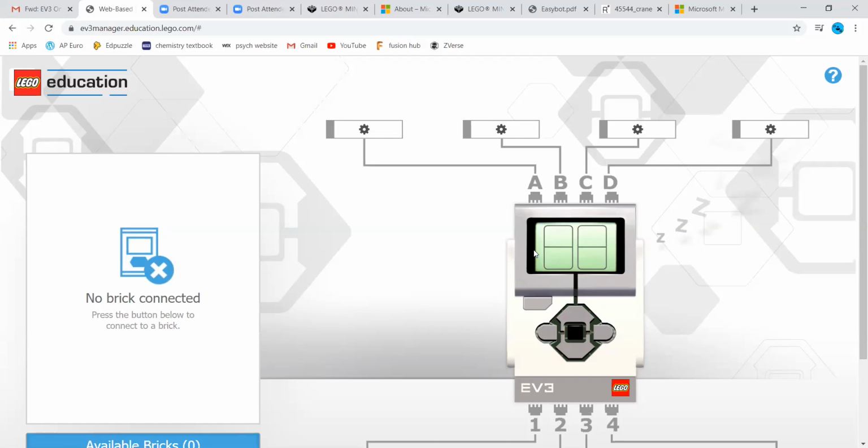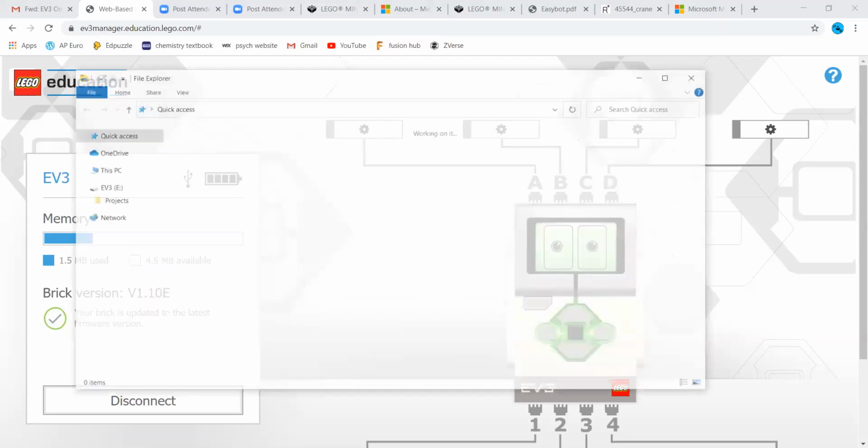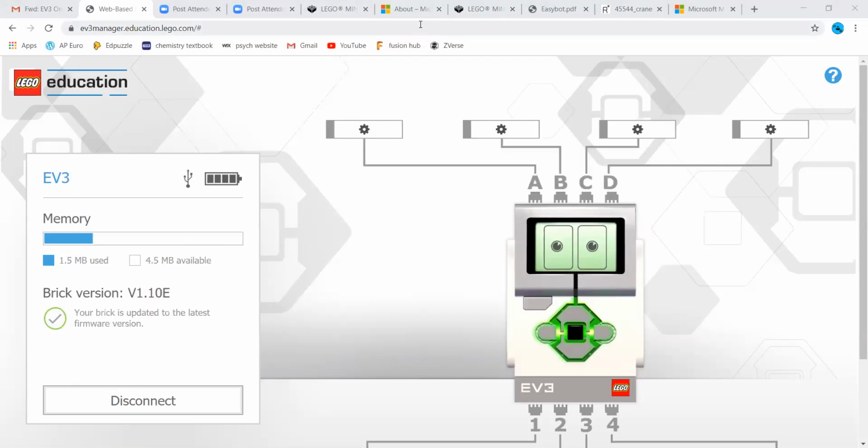Now do I just click update firmware? Yeah, so what does it show? Does it say 1.09 version? 1.09H. Okay, so it needs 1.1 to run with MakeCode. So you're going to click update firmware. Update now. It's updating.